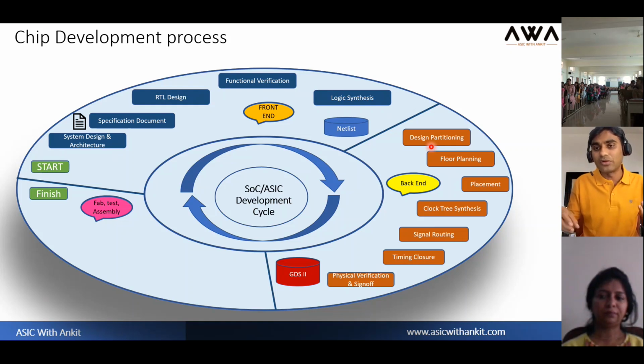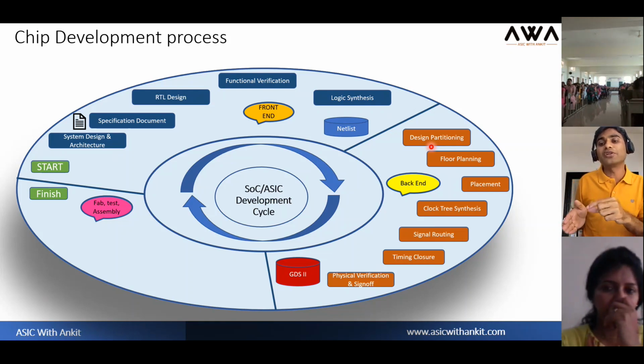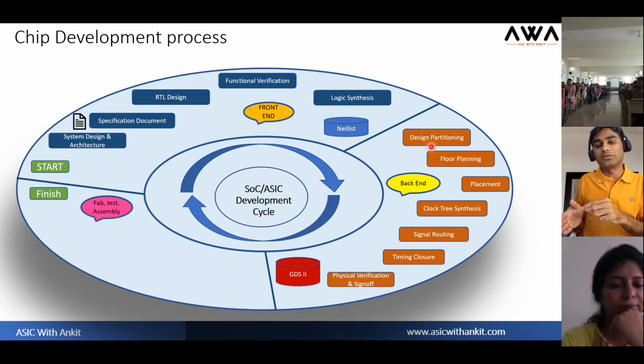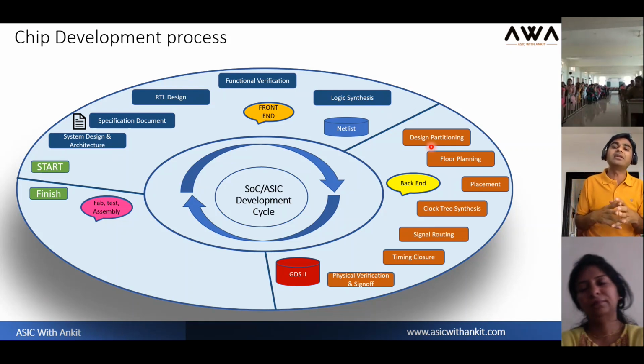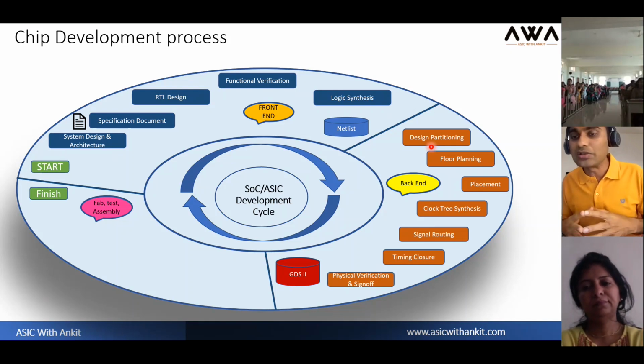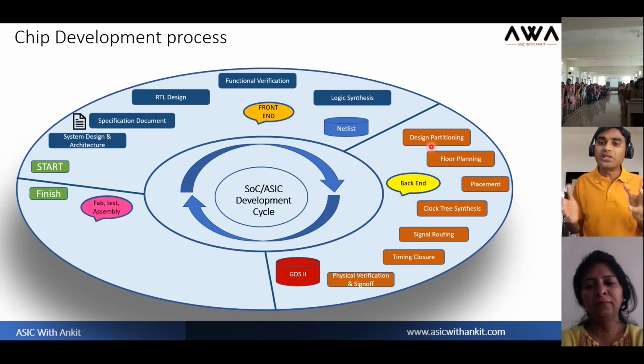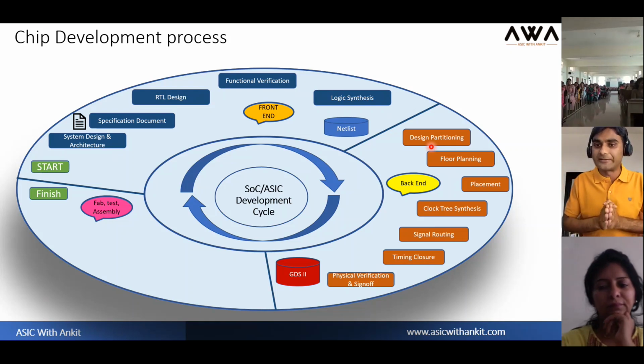And if some blocks are closer to the input and output of your circuitry, then put those blocks closer to the IO functionality. That is something we call an optimization. We intelligently identify those blocks to stay closer, so we optimally partition, floor plan, and place together during this physical design process.